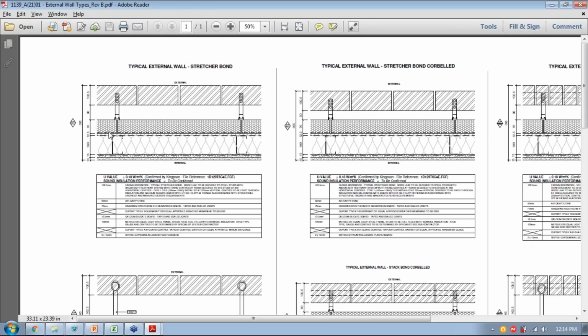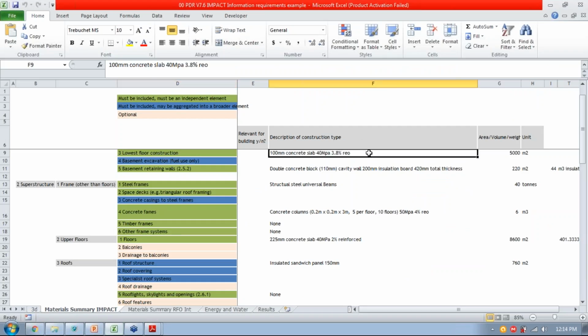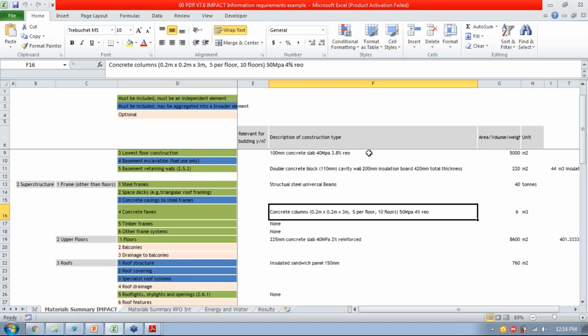We've got some cavity firm insulation there. We've got some silicate board, some Metsec, so steel studs essentially, and some plasterboard and insulation there, double layer plasterboard. So that's the kind of information that I need, the thickness of the materials and the type. All of these thicknesses are pretty standard. I want to make a note though of the insulation thickness, which is obviously going to change.